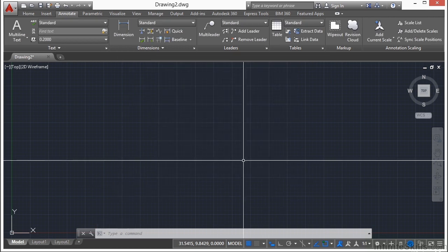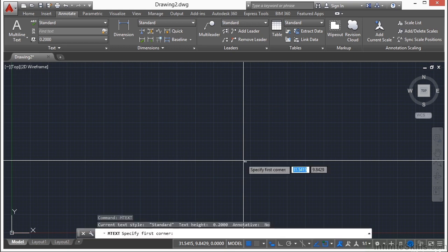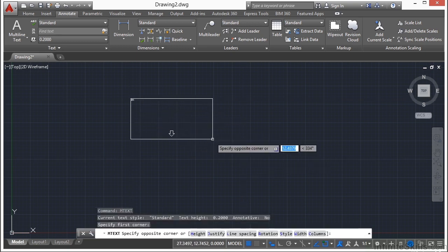Now, as I stated earlier, there are different ways to use text in multi-lines, and you need to let your styles control your font type. M-text objects can be edited within the text editor, but once you do, you lose some of these controls or abilities. For example, let's load in some text, and I'll show you a trick on how to load some text. So we're just going to start the M-text command.